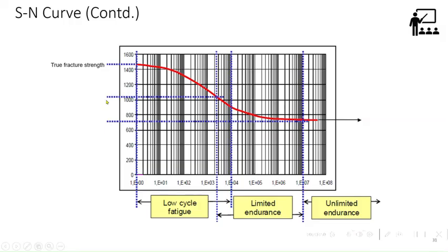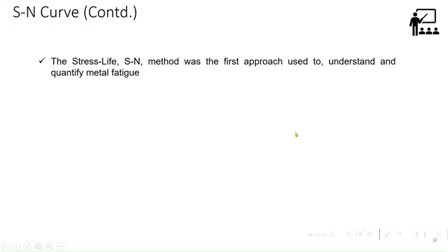Then if you do another specimen with lesser stress, it will take more number of cycles to failure. When it comes to yield point, beyond any yield, you will have plasticity. And of course, this is for ferrous material. You come to somewhere, of course, showing 10 to the 7, doesn't matter, but benchmark is 10 to the 6. There's no issue. So endurance limit is below which you will have an infinite life.